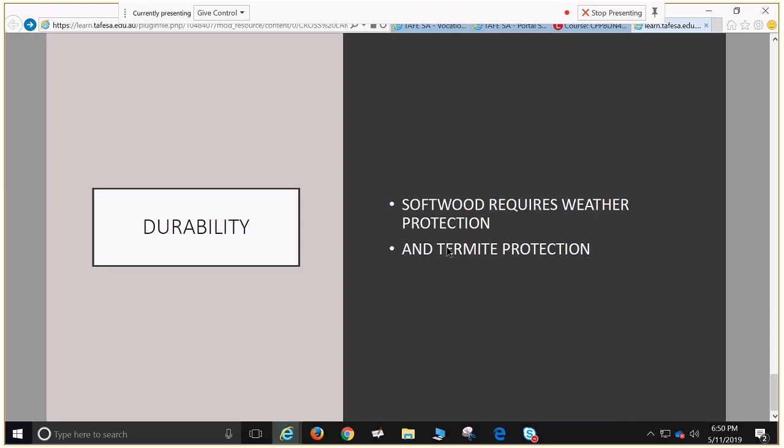So typically with things like timber trusses or so, if you've got termite protected timber to your frame, well then it doesn't matter about the trusses because they're not going to get to that point. But with a product like CLT, because it's flooring, walling, and roofing, you need to have a continuous termite barrier to the building.